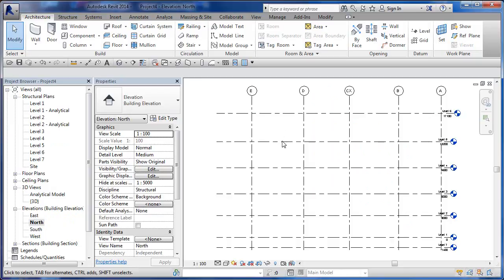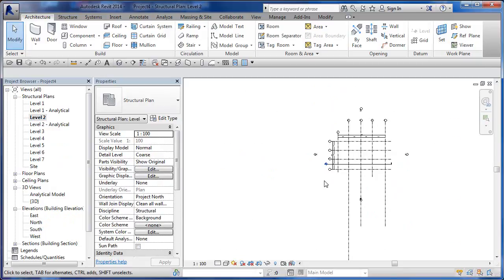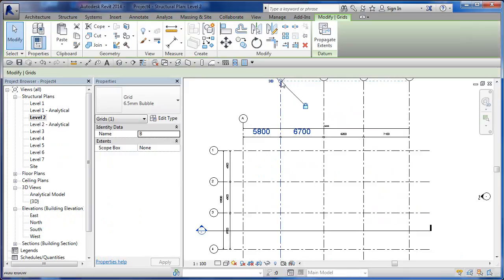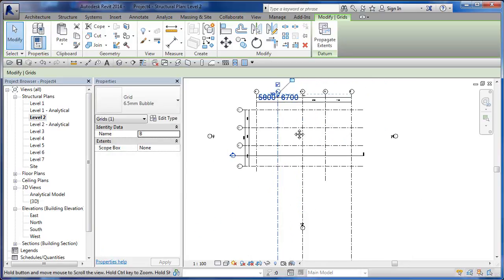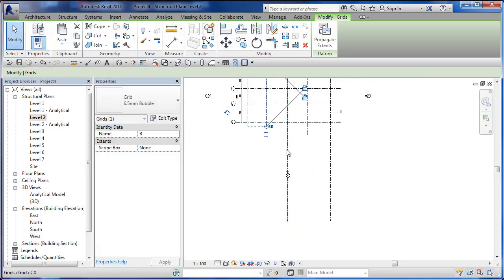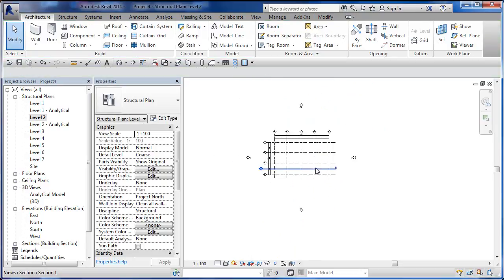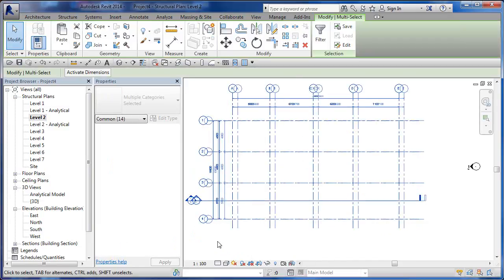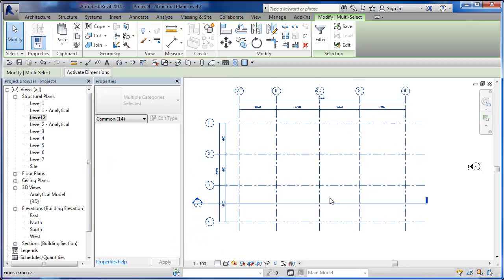Okay, and grid lines are visible. Level lines are only visible from plans and sections, but grid lines are visible from elevations and sections and floor plans. All of them. Okay, it's like a big vertical sheet. So the reason why we're spending so much time on this is, of course, in Revit Structure, our structural system and our beam systems and our footings and our columns and all that stuff is all very heavily tied to grid lines and level lines. We're going to see that as soon as we start to get into some of the drawing. I'm just nudging them over with my arrow key.